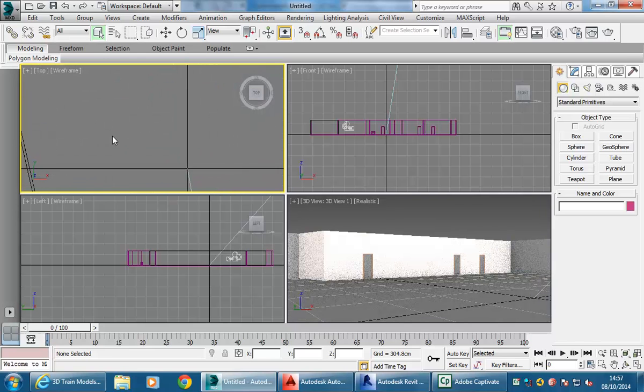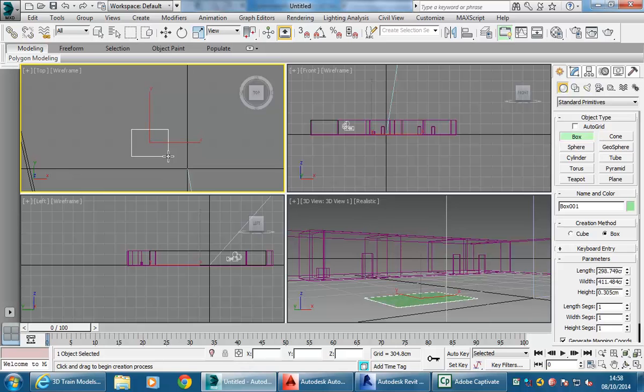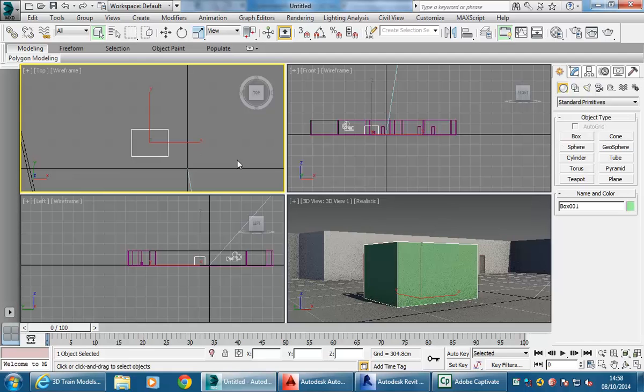And now if you remember the way that I showed you, you can start modelling, this is positive modelling, with polygons. Often you can begin with something as simple as a box. So I'm just going to, with box over here in the main command panel, click and drag to make something in the top view that I can see in the perspective. Bring that up, and I've got my basic form. So then right click and it'll finish creating it.